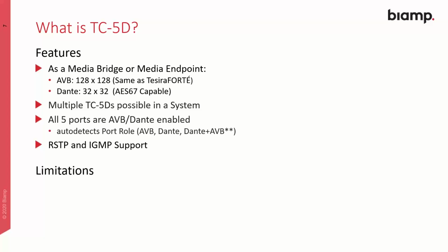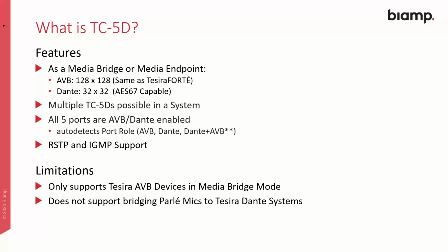Some limitations that would be good to be aware of, these are notable. Only AVB devices that are Tesira are supported in media bridge mode. Okay, so if you're bridging Dante and AVB, only Tesira AVB devices will be supported in a design like that. It is not possible to bridge Parlé mics into a Tesira DAN system. Parlé mics use back-channel communications with the DSP over the AVB channel, and this is not currently implemented in Dante. That said, all other AVB peripherals and expanders are supported.